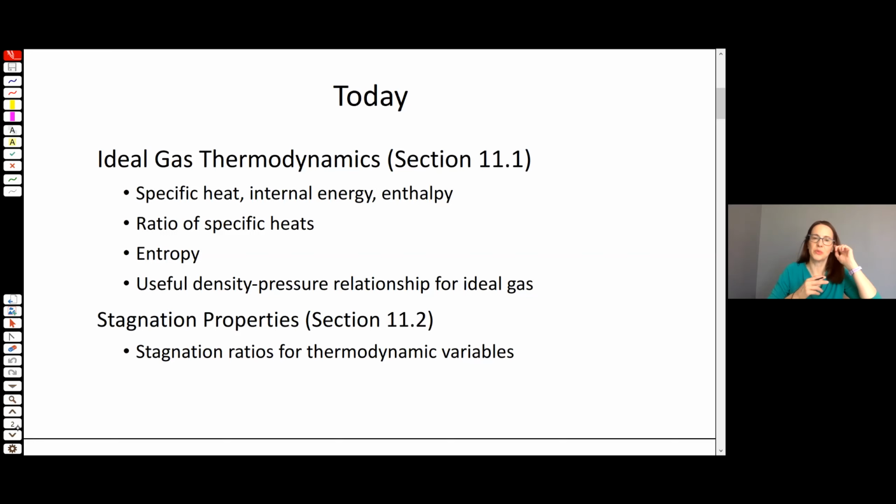But here we'll do a quick refresher about the quantity-specific heat, internal energy, enthalpy, and some other thermodynamic variables, including entropy, and derive a lot of really useful relationships. And then we'll also talk about stagnation properties, right? If you bring a flow to rest, you can write down expressions for the thermodynamic variables in terms of the flow that's at rest.